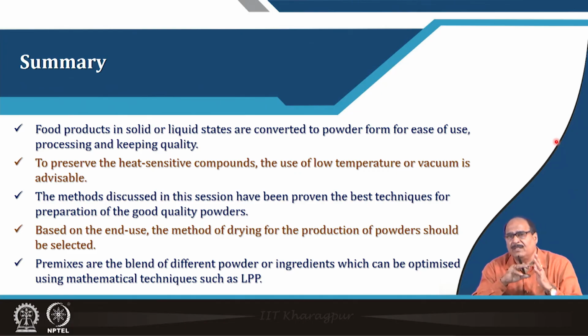So, they should not be subjected to very high temperature in the drying process, otherwise, whether it is spray drying or drum drying or belt drying, it will create a problem of stickiness, etc. So, proper care has to be taken in spray drying, suitable design arrangements are made, or one has to go with lower pressure vacuum spray drying or vacuum freeze drying, etc.